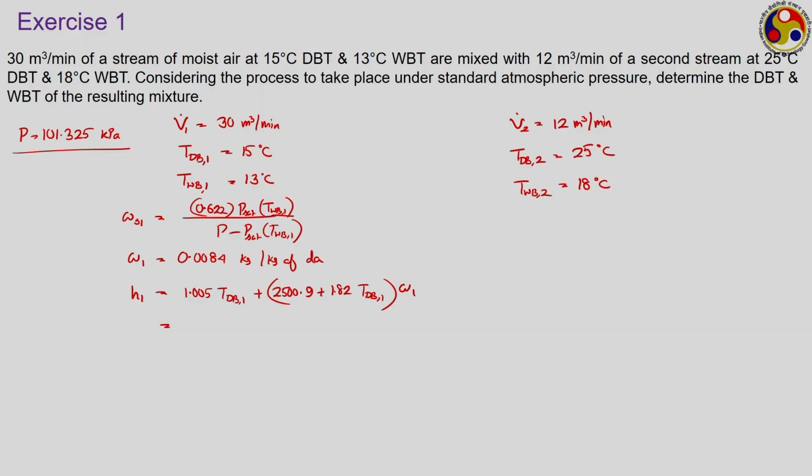Remember, here these temperatures are put in Celsius, that I keep on repeating because this is a deviation from whatever convention that we have followed so far. So, accordingly we are getting the value of enthalpy to be 36.85 kilojoule per kg of dry air.